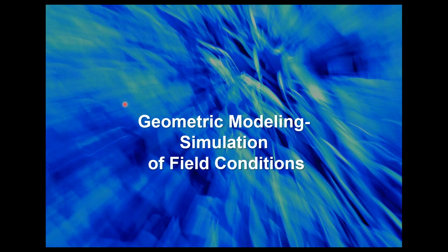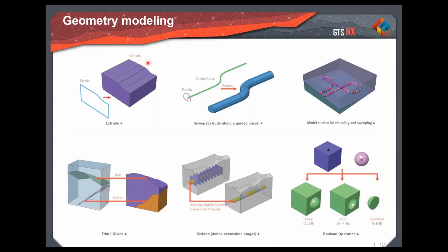The very first step, as I was saying, is geometric modeling. What the features and modeling capabilities in MIDAS GTS NX are will be explained to you now. So this is geometric modeling. There are many methods to model the condition. One particular method is to use the work plane: we model in the work plane, and then we extrude it for the 3D structure. Or else we can directly go for the three coordinates X, Y, and Z and model. Otherwise, we have different wizards in order to model the feature itself. All of these are easy to simulate in GTS NX.